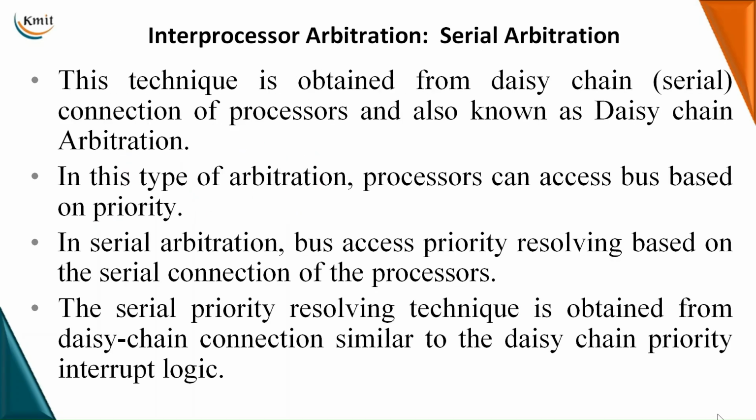The first technique in static arbitration is the serial arbitration technique. We can also call it daisy chaining arbitration because this technique is obtained from the concept of daisy chaining priority. Do you remember? In a priority interrupt, we come across daisy chaining priority. Based on that technique, this arbitration technique is designed.